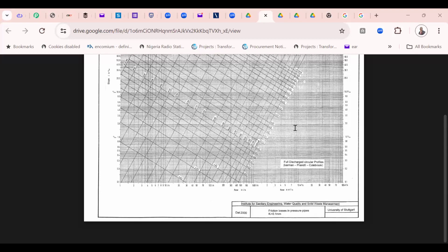That is the main. But now this is the point. That pipe size is just the main. As it enters, say you want to go into Ademola Tokumbo, you can reduce it to 150 based on the population of people on Ademola Tokumbo. As it's entering smaller streets, it will turn to 100. But the main is like the head. If the head is wrong, all the other parts of the body are wrong.